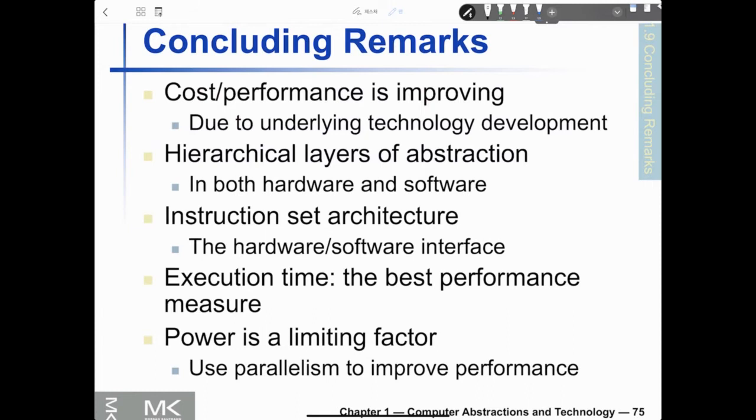We also learned what a clock cycle is. And power consumption is proportional to the square of the voltage. Due to the power consumption and heat emission, we cannot increase the voltage anymore, actually we are dropping the voltage. Instead, we are improving the parallelism, adding more components to improve the performance. That's the modern approach.